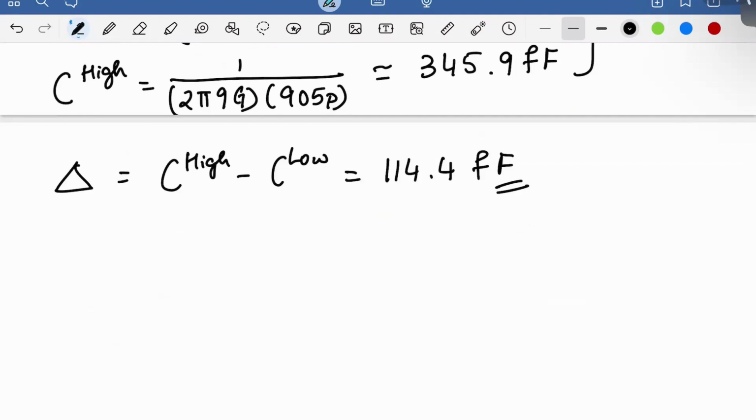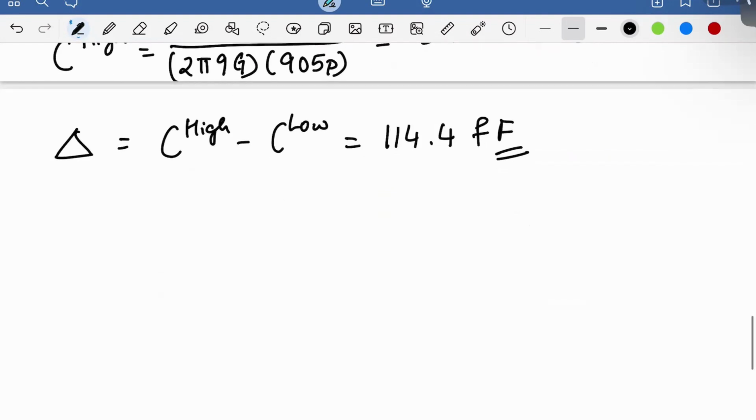And that depends on what the slope of the fine-tuning capacitance is. We'll discuss the slope of the fine-tuning capacitor in more close detail when we discuss PLLs. It has to do with the KVCO of the varactor. But in this case, let's just say we want to divide this into 8 different voltages, which means that's a 3-bit discrete tuning.